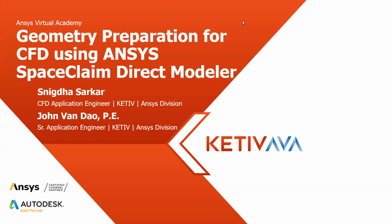Today, we will be covering geometry prep for CFD using SpaceClaim Direct Modeler. This session is geared towards anyone who is starting off with either CFD or SpaceClaim, or just looking to simplify their workflow in setting up a CFD simulation. So hopefully by the end of today's session, you'll be able to extract flow volumes from your CAD geometry.